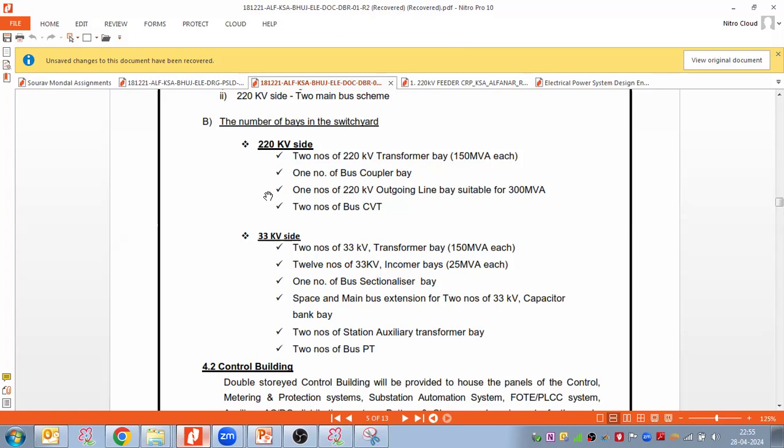In the closed loop, if we are distributing power supply through RMUs, the power supply from one feeder from the substation goes to an RMU, then another RMU, and then comes back to the same substation, connected in a different bus: bus A, one feeder, bus B, another feeder. So this loop is closed. Is there any issue if we keep both feeders closed and power supply continues? There is no problem, correct? Any dead short circuit?